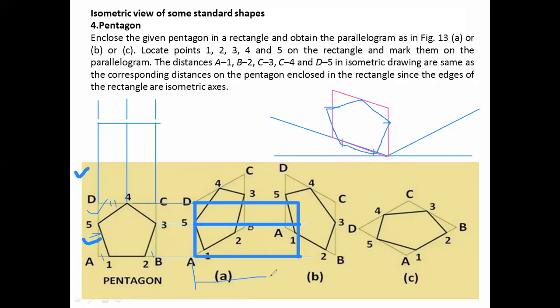Fine. Now you know this is 50 mm, for example. So you draw this line for 50 mm. Every line we will draw up to 50 mm, parallel to this line. 1, 2, 3, 4, and 5. But instead of that, what is better? Just a moment. A better idea is to draw one more square at 50 mm distance. Understood? So it will be this way, this way, this way, this way. And now draw the projections. We know how it will work.